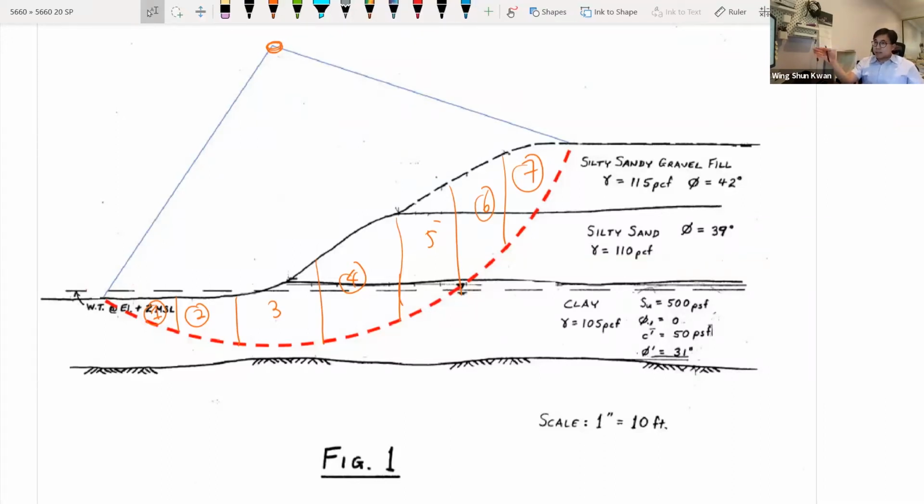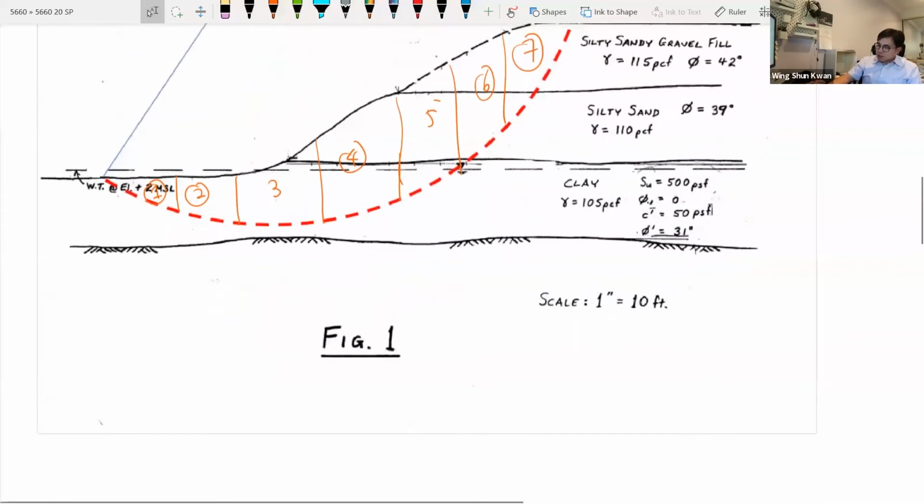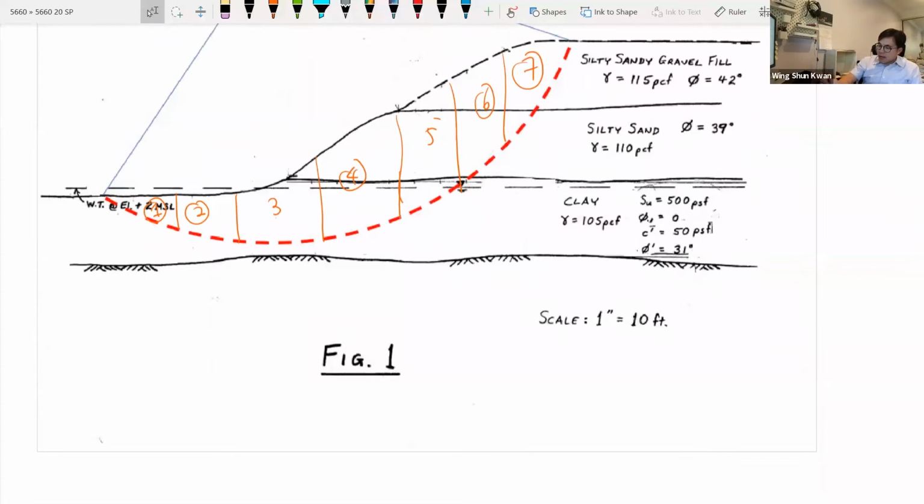But you understand that at some point you will get saturated, which means n versus n plus 1 slices, there's not much difference. For example, 10 slices versus 11 slices, the difference will be very, very small. But anyways, 6, 7 or 8 slices should be sufficient. So on each slice, you can have the parameters you need.